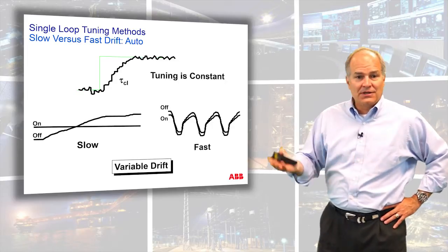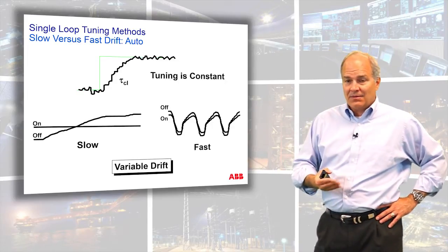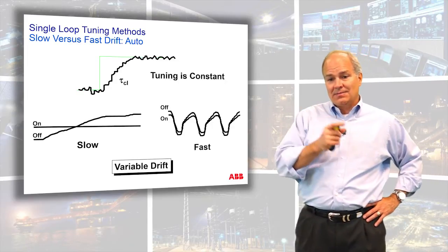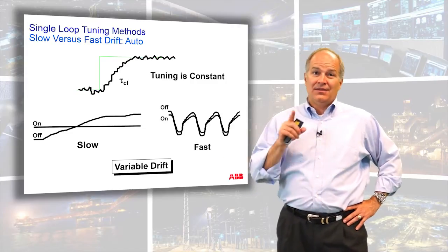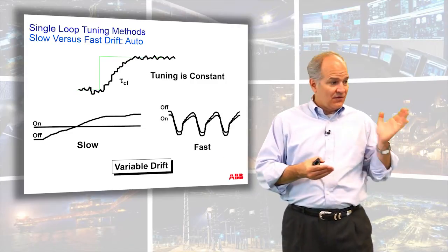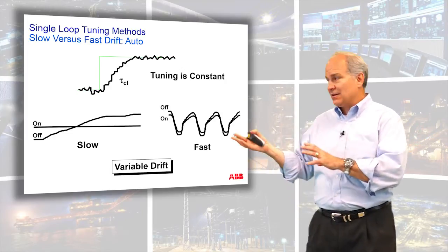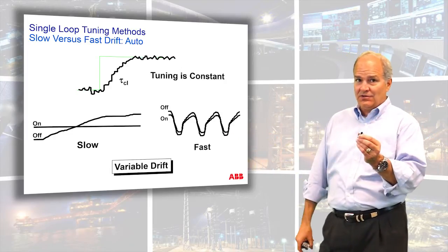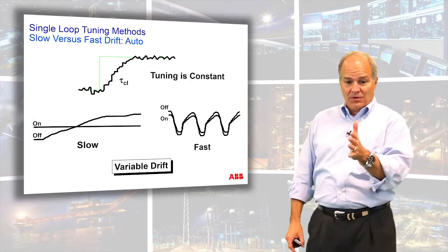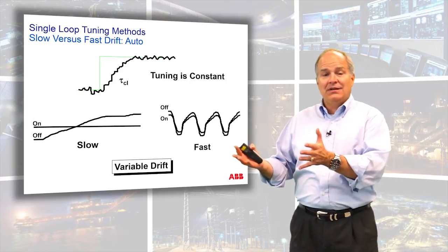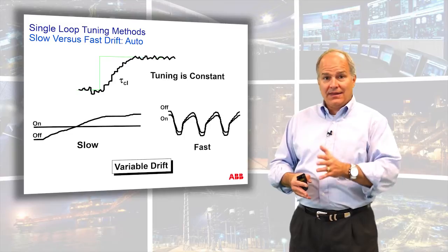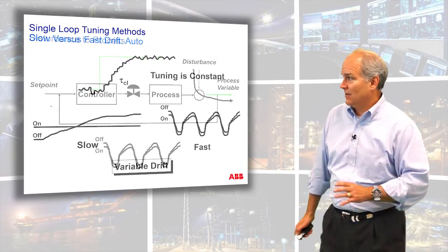And then people will go retune it. Maybe that's not the problem. Maybe you have a disturbance that is passing through your controller. And the real trick isn't to retune it, it's to go find the source of the disturbance and fix it there. That's the beauty of what we're about to talk about: if you know how you tune the loop, you can calculate the point at which your controller's ability to attenuate goes away. And then it's process design, and that's what gets to be fun.